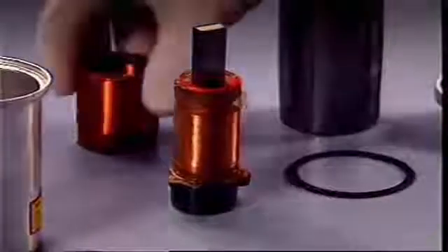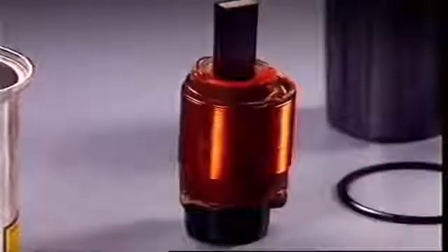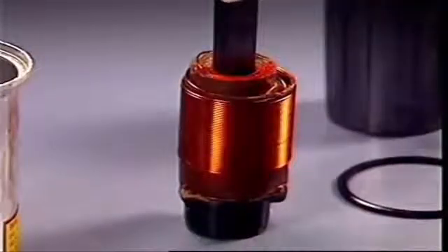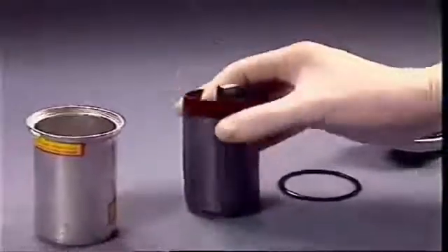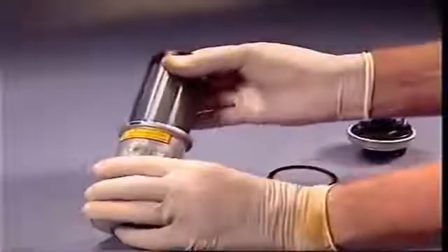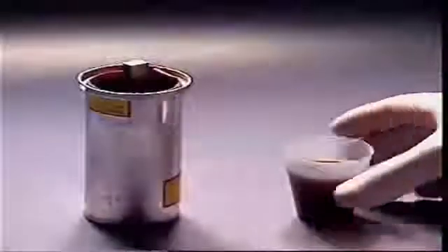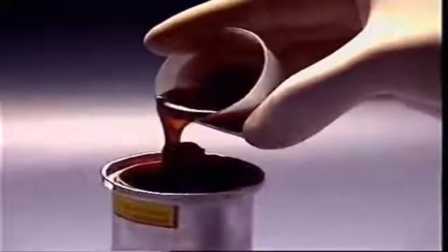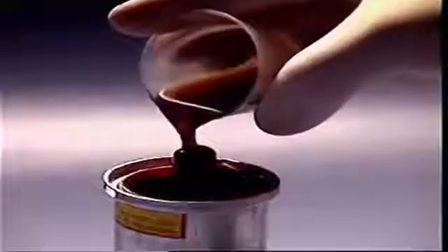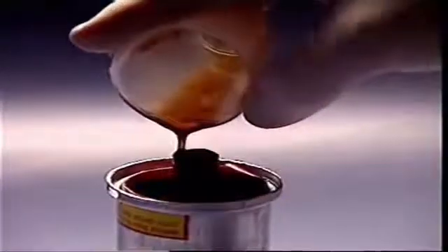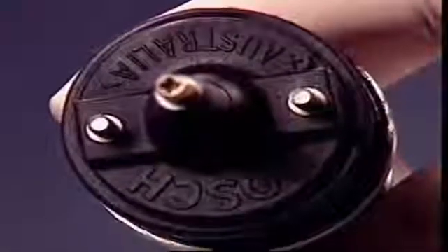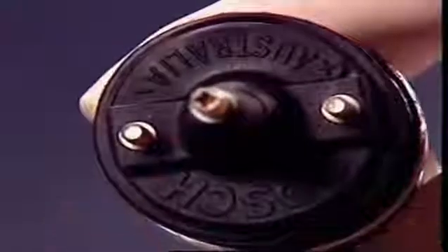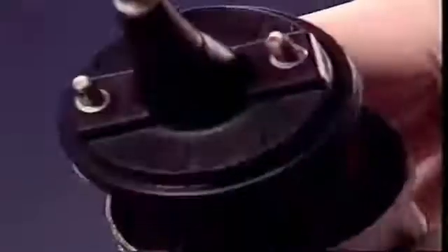The primary winding, with a few hundred turns of much heavier copper wire, is wound on the outside of the secondary. A shield of soft iron surrounds the outer windings, and the complete assembly is inserted into a one-piece steel or aluminium container. The container is then filled with a special transformer oil, which provides good electrical insulation and also permits rapid heat dissipation. The cap has two terminals, positive and negative, for external connection to the primary circuit.